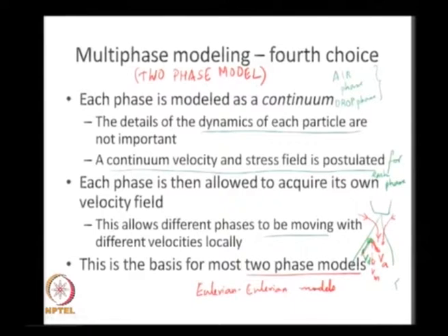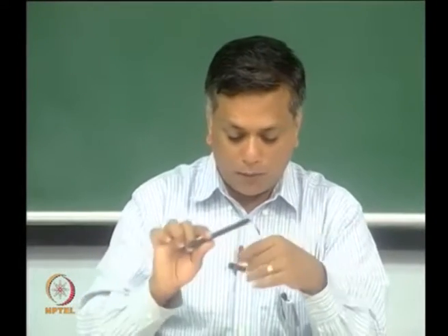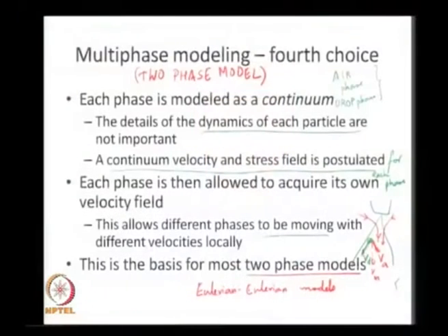Okay. These two-phase models rely on the assumption that I can take all the bubbles and postulate a continuum phase comprising of all the bubbles. Okay, so, this is essentially the fourth modeling choice. So, now we have learned 4 different ways of modeling multi-phase flows.